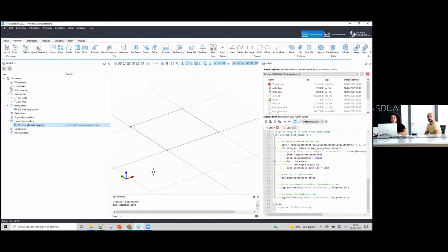Then we have another question: how can we consider adjacent buildings or structures in our models? Well, it really depends on how you want to consider them. For example, if you want to see if adjacent buildings touch each other during an earthquake, you cannot simply put them one next to the other, because they are two separate geometries, so OpenSees will not perform any kind of contact detection.